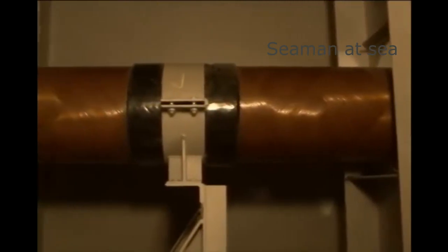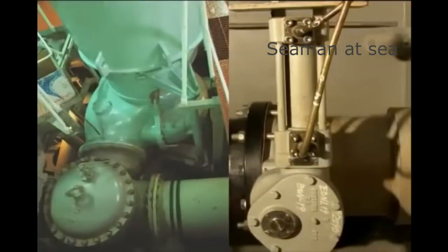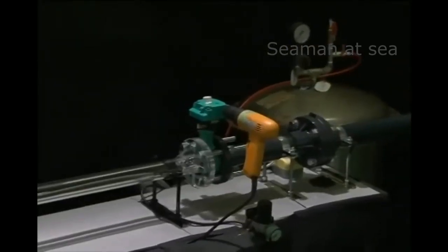If flow velocity within the pipeline suddenly changes due to valve operation at the start of or during pump operation, the pipeline internal pressure increases momentarily but sharply. This phenomenon is called water hammering. Water hammer can damage the pump casing, valves, and pipeline. Shown here is an experiment reproducing the process of how water hammer occurs.